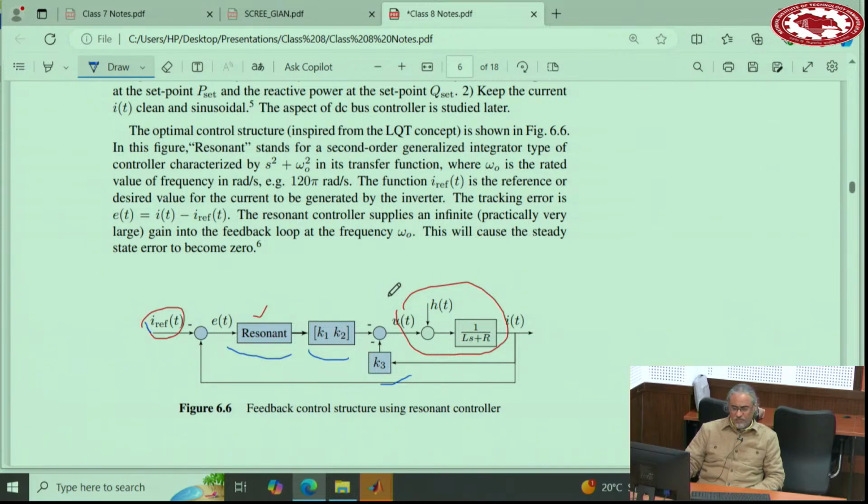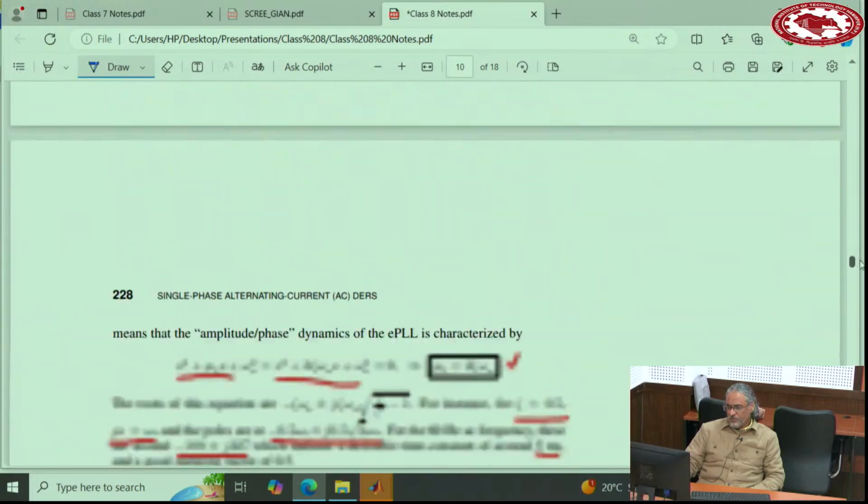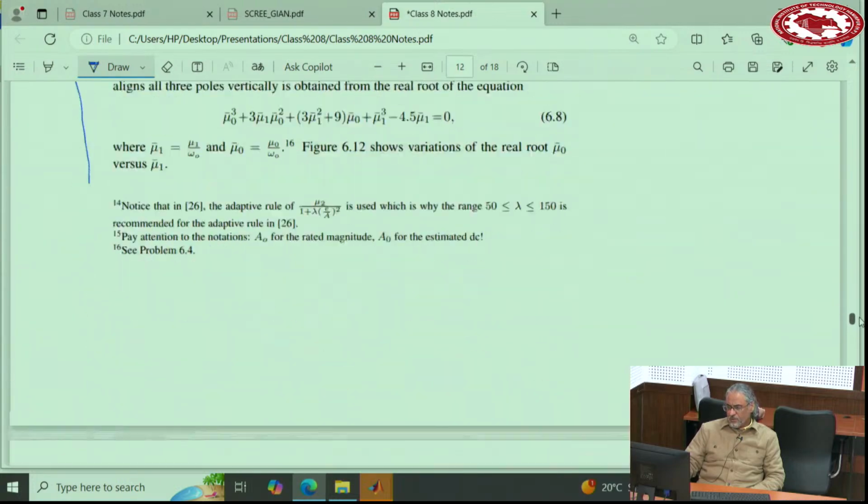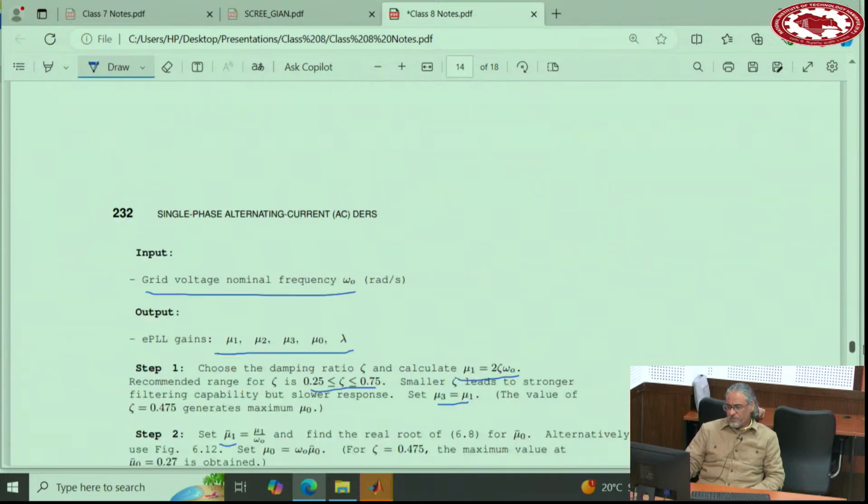Of course, we used PLL for the feed-forward term here and also for the reference current. So we discussed the PLL in detail. We discussed how to limit the current also. Next and the last step would be to design K1, K2, and K3, the controller design, which by now should not be difficult for you to do. Just writing down the equations.